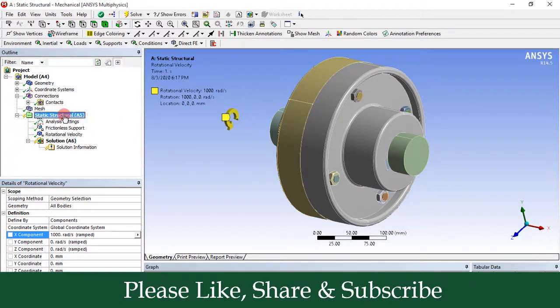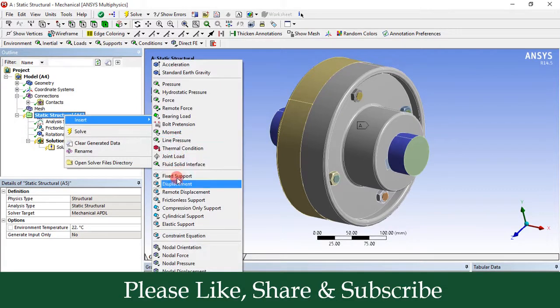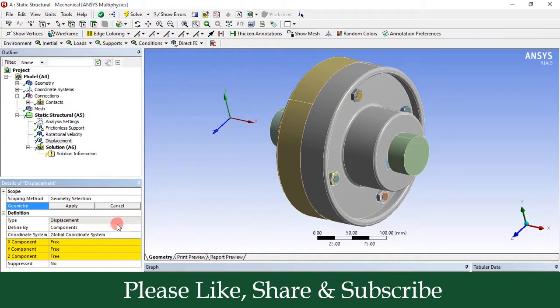So again, go to the static structural, right click on it, go to the insert, go to the displacement. Now we have to select the face of this model so that its displacement along x axis can be restricted. As there is a possibility of displacement along x axis, I will select the face button, I will select the face of this output shaft, and I will click on apply in order to apply the geometry.